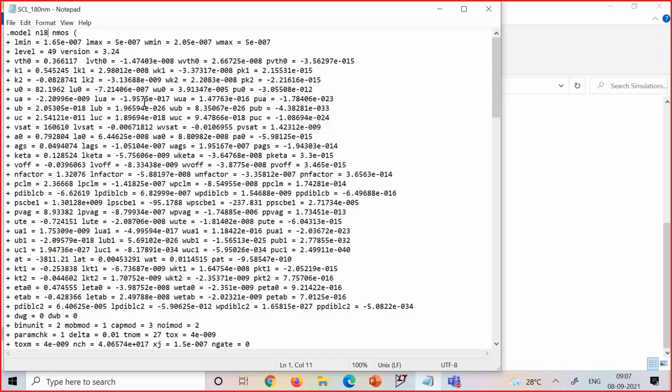Now, such an equation really is a very approximate one. In fact, as I mentioned in one of the earlier classes, the threshold voltage itself will change slightly as a function of channel length, right? And also the mobility and other things keep changing.